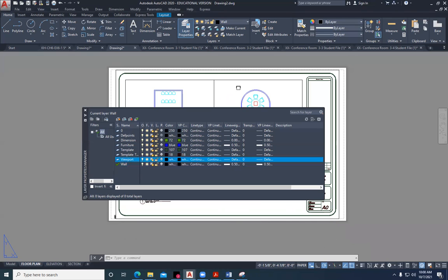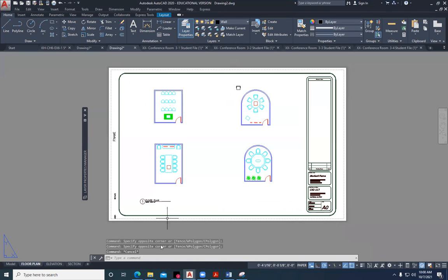And then I'm going to set that scale at 1/8 of an inch and lock it. Come into the next one. And again, they're like windows or TV cameras into our model space. Line that up, dial in our viewport scale, and then lock it. And then lastly, dial in our viewport scale, and then we'll lock it.